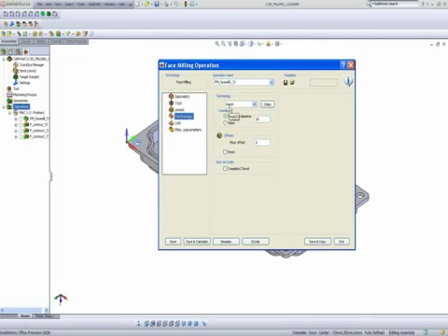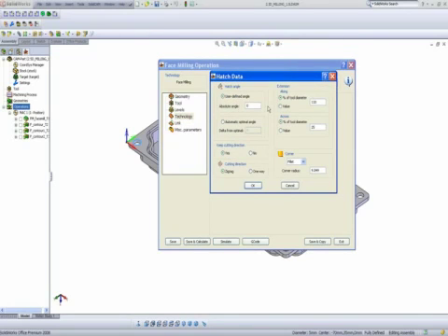My technology, again, I'll be using the hatch, but this time, just to show you the difference in what control we have, I'll use my absolute angle as 90 degrees. So that the tool will actually go 90 degrees across the part instead of 0 degrees.